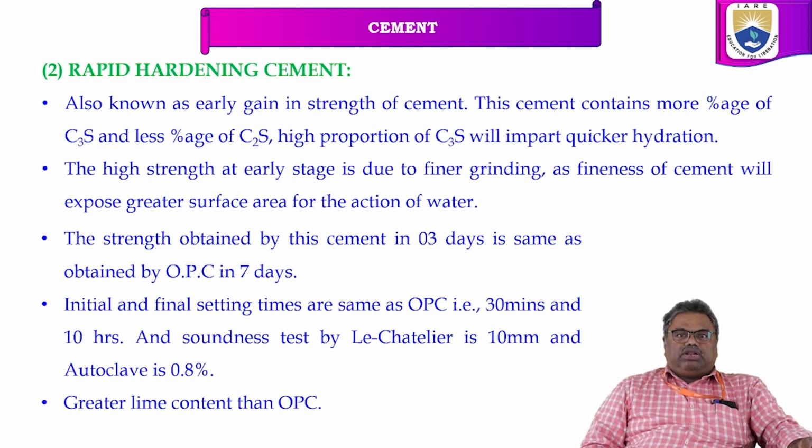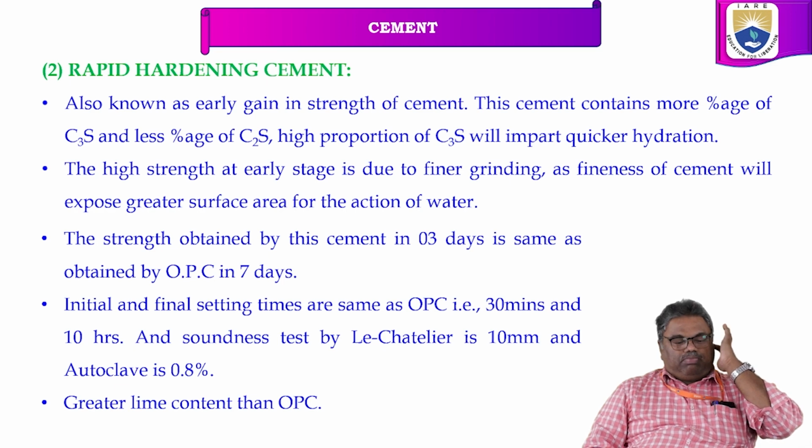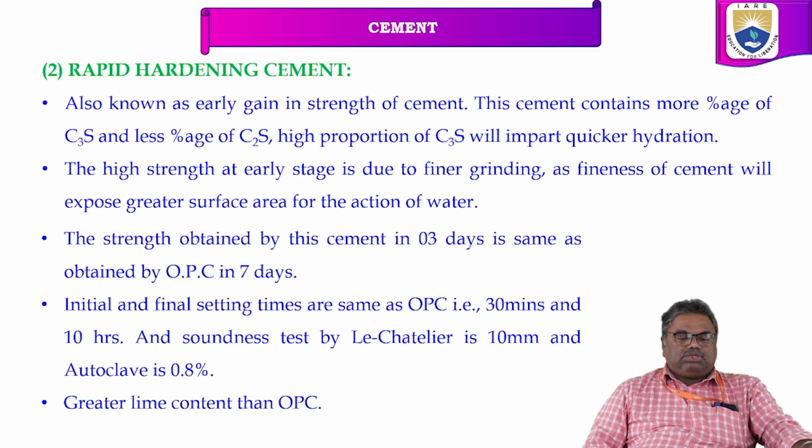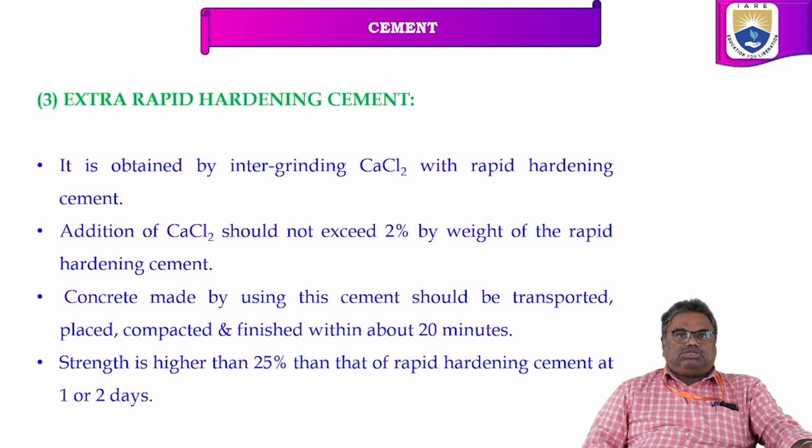Initial and final setting times are the same as OPC. That is, the initial setting time is 30 minutes and the final setting time is 10 hours. The soundness by Le Chatelier is 10 mm, and by autoclave it is 0.8%. It also has a greater lime content than the OPC. So this is about rapid hardening cement.